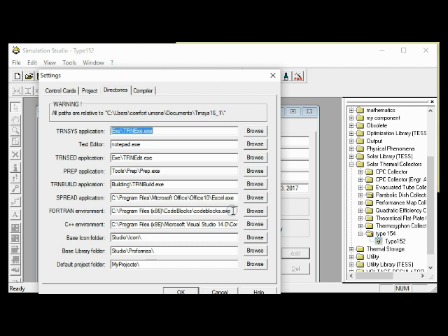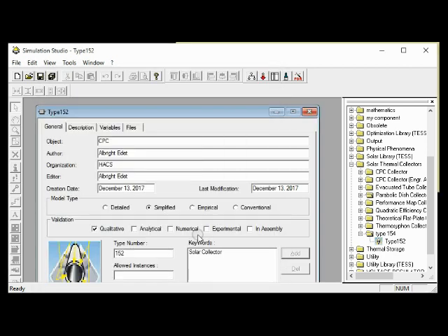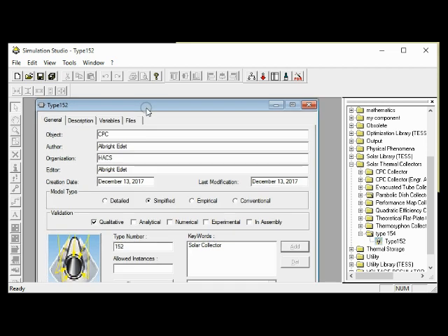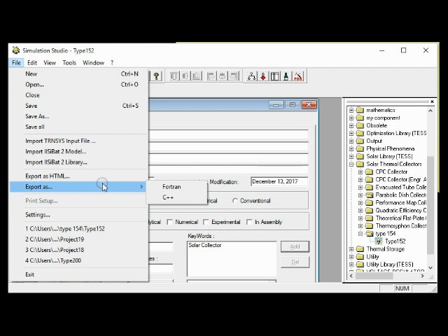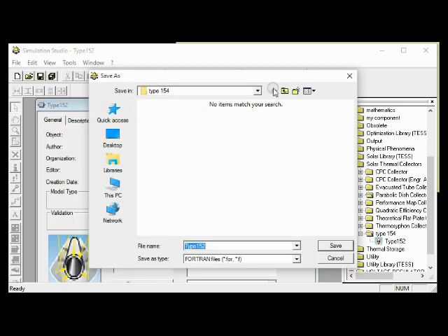So here I use Code::Blocks, but we both know from the beginning the requirements for creating a new component to work within Trnsys, which is under the Programmer's Guide. You need Intel Visual Fortran and Visual Basic. You install Intel Visual Fortran into Visual Basic and you call up the path here, like C program files, Intel Visual Fortran, whatever it is, .exe, so that whenever you want to export this file, it will call up Intel Visual Fortran, from which you edit the Fortran code and create a new component. So for now, I have Code::Blocks here, so I'm going to show you how this works.